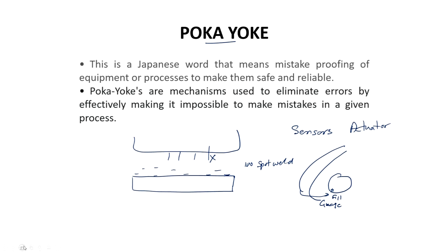What is the new method? Now, you set the pressure on a dial, you say you want a pressure of 35, you set the pressure of 35 on the dial, insert the nozzle, and as and when the pressure of 35 is achieved, the air supply is going to get cut off. So, that is the kind of Poka-yoke we are having, and all your home appliances etcetera also have a Poka-yoke, where when the desired temperature is achieved, the supply is cut off. So, that is the concept of Poka-yoke.